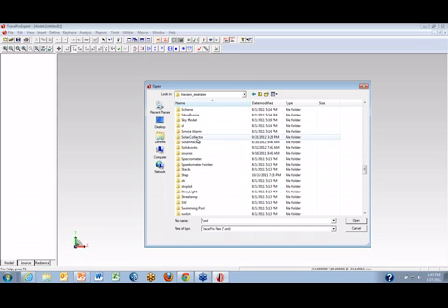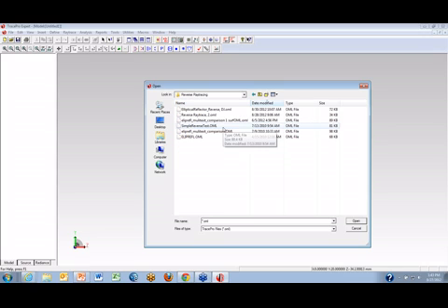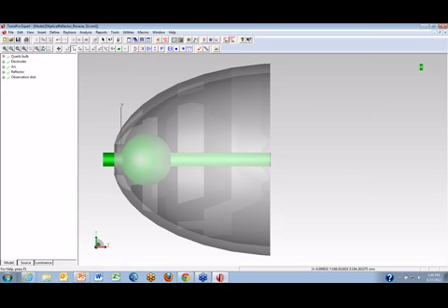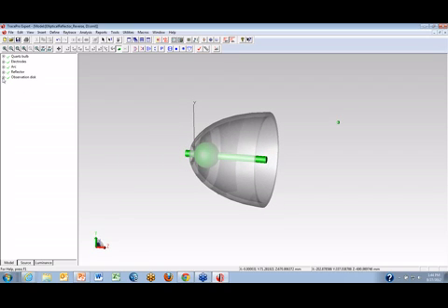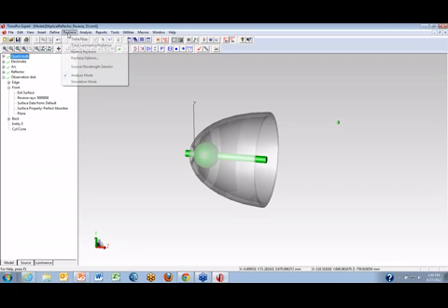Just make sure you actually are tracing a symmetric object. The one example I'm thinking about is somebody was doing a light pipe application where they had 2 light pipes that were offset from the center, and when rotational symmetry was applied, you wind up with one large blob of light instead of 2 individual spots of light. Yeah, that is a definite problem. You don't want to do symmetry when you don't have those conditions.